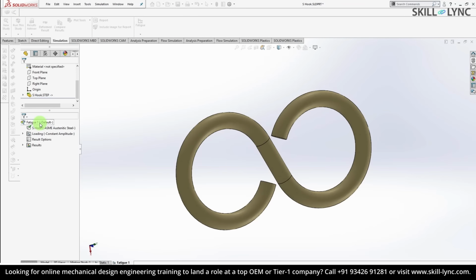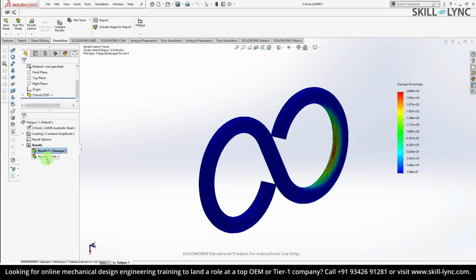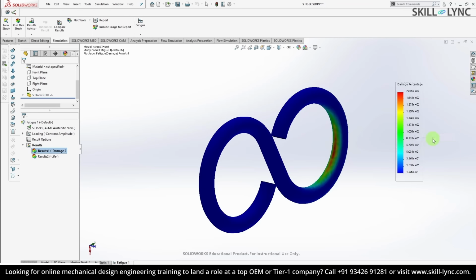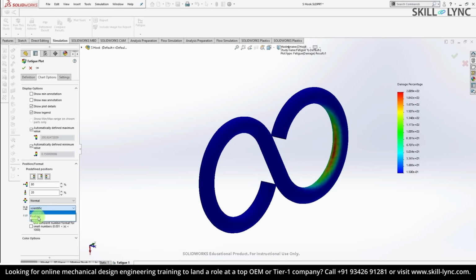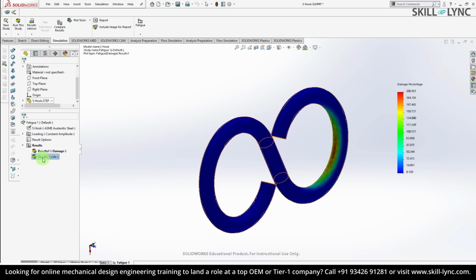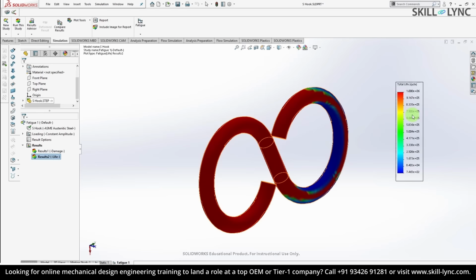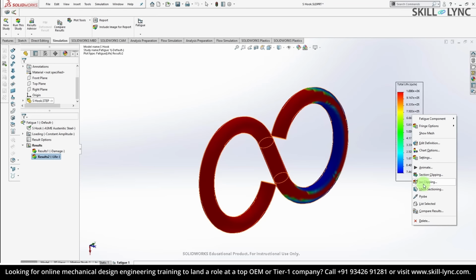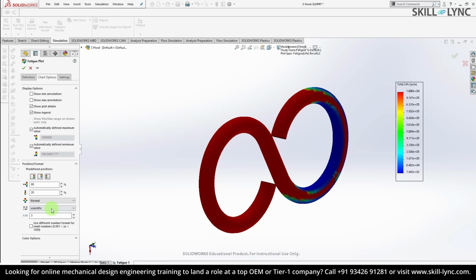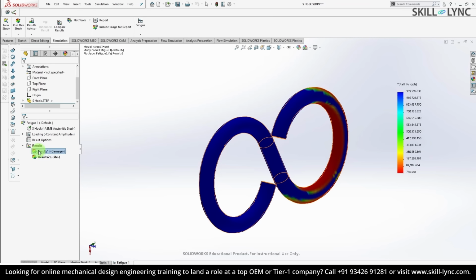Let's run the simulation here, and we have got the damage as well as the results live. Before we could infer anything, right click on the legends, click chart options and change the scientific notation to floating. Click OK. Now for the results, right click show. Similarly, right click, do chart options and change it to floating. Click OK. So first let's have a look at the damage.